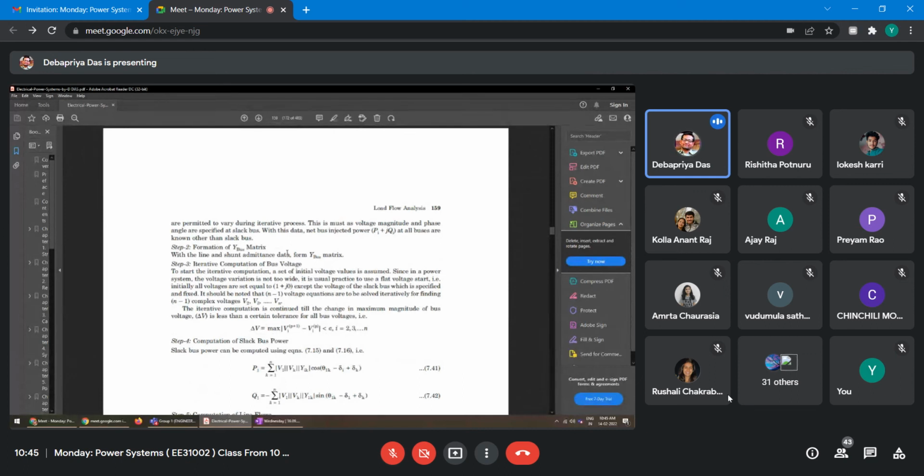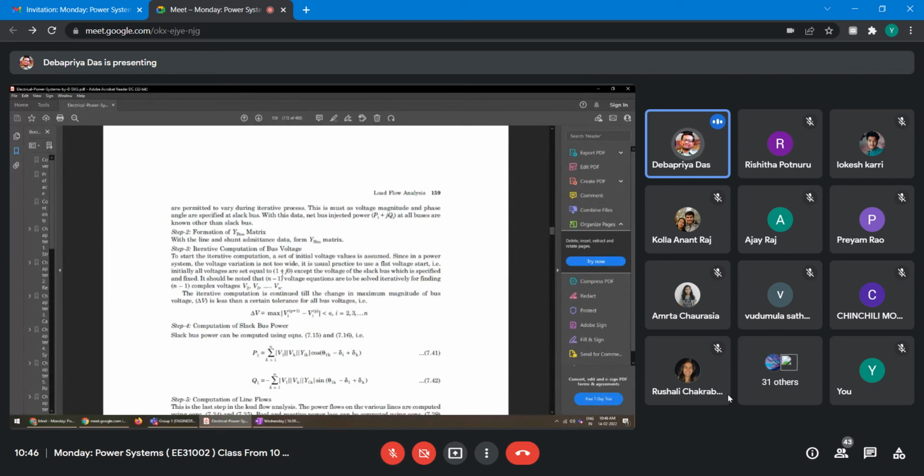And after that, all these equations for the Gauss-Seidel method, the V2, V3, Vn equations, you put in a loop, and all these equations will be computed. It is not like you have to write each and every equation in the code. Just for i equals 2 to n, you write it in general and it will come automatically. And after getting all these voltages, you take the current value of the iteration minus the previous value, take the magnitude, and see the max of that to check whether the solution has converged or not.